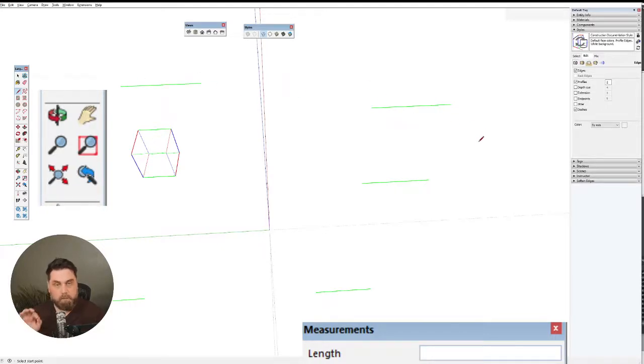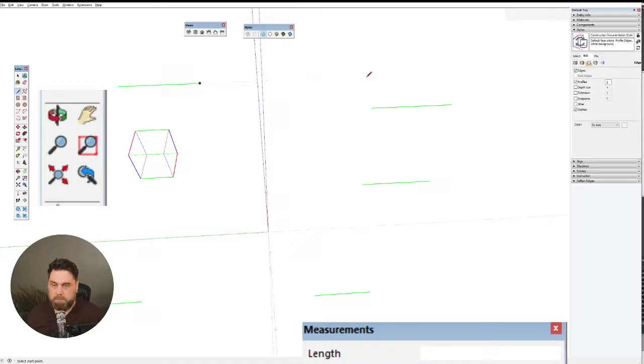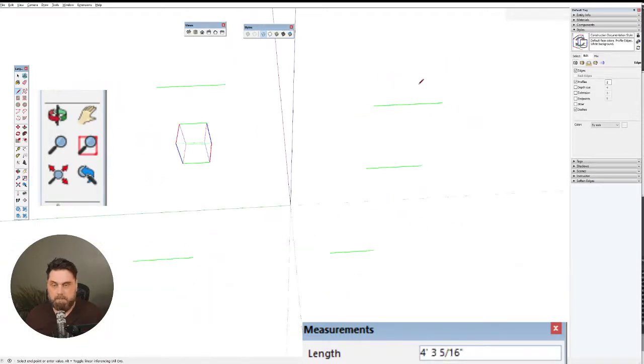And this is what we want. If we're drawing a patio or a house or anything, we don't ever want an edge to be like that. If it's black like that when we're drawing it, that means it's off axis. That means it's out of square, out of plumb. It's no longer going to give us true 90s as we go about drawing.